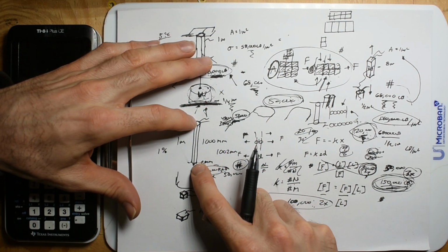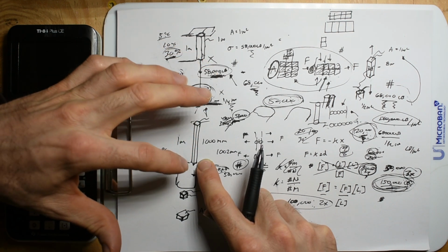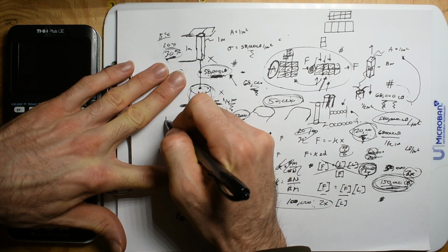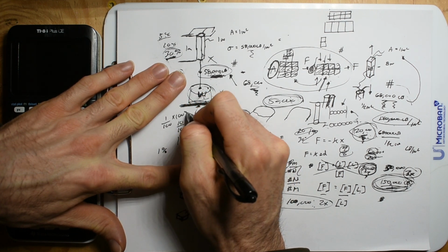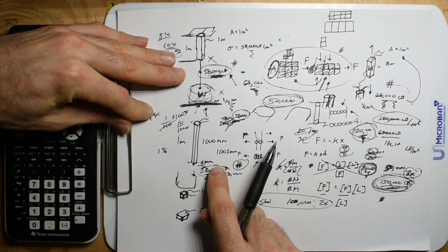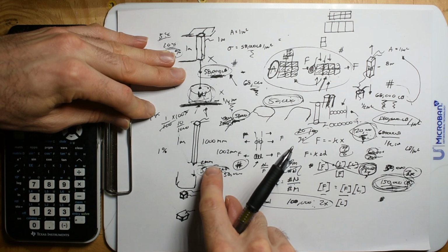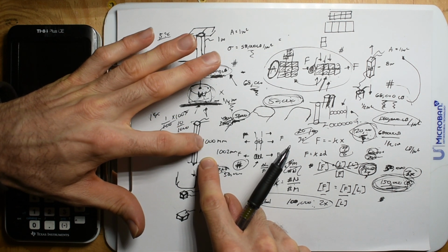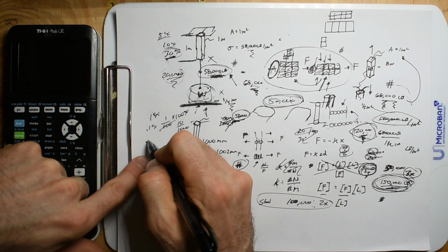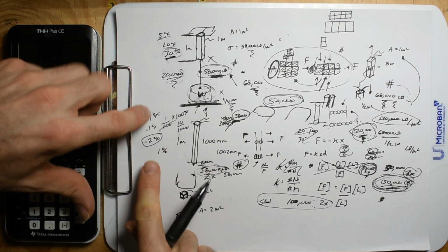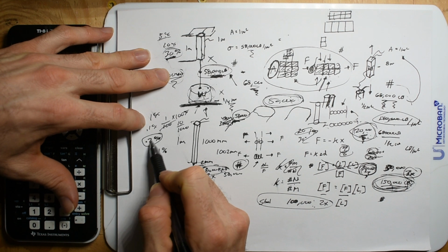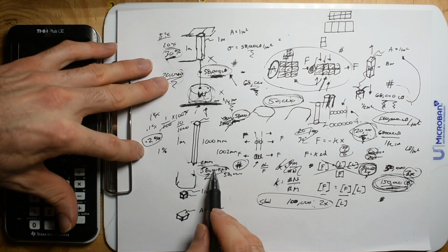So if I stretch this 1 meter steel bar, 1,000 millimeters, by 10 millimeters, I would have 10 divided by 1,000, which is 1 divided by 100, multiplied by 100%, and then I got 1%. So that can be easy to see. What if I stretched it 1 millimeter? Well, that would be 0.1%. So if I stretch it 2 millimeters, I'm stretching it 0.2%. And hey, that number is not too small. Your brain's not gonna get fried with 0.2%.